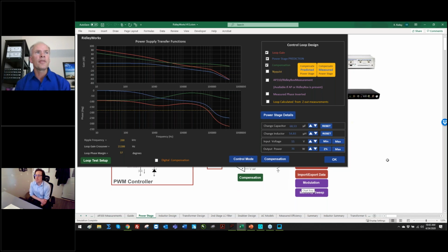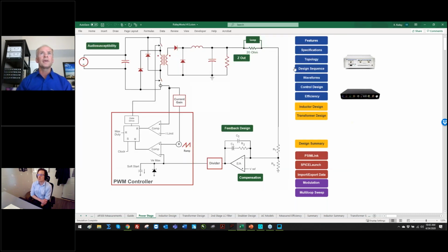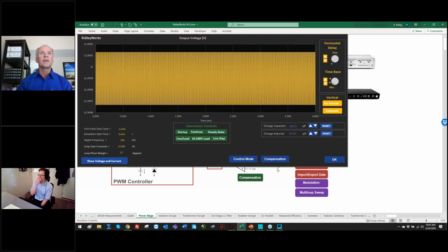Inside our program, the crossover target for a buck-derived converter is 1/10 switching frequency. The phase margin goal is 50 degrees worst case. Okay, so if you can hit that for a real converter under all conditions when you're doing your prototyping, you've done a pretty good job. If it gets below 50 degrees, you start getting a bit nervous. Theoretically, is it still stable? Yeah, of course it is, but here we can go look at the meaning of that phase margin.